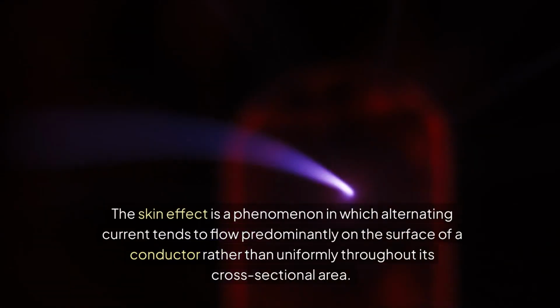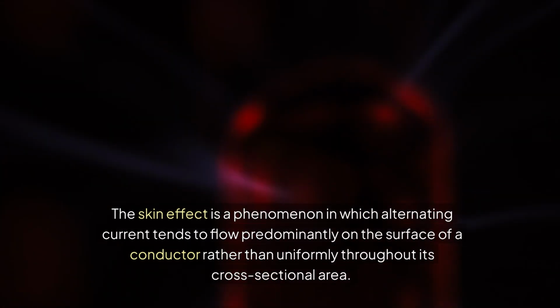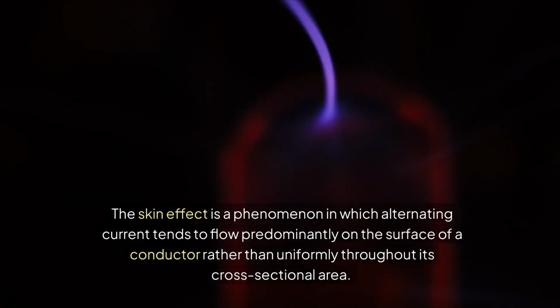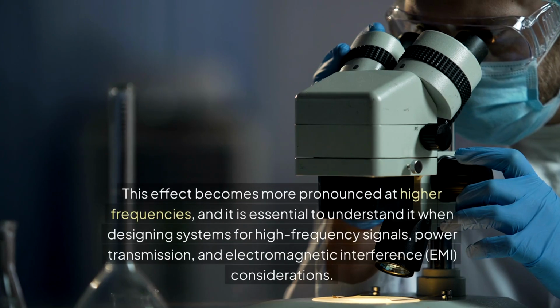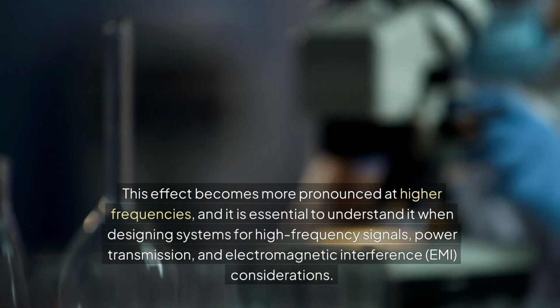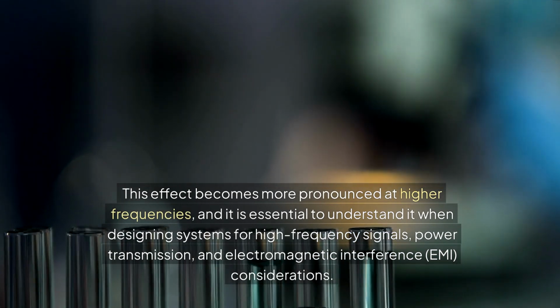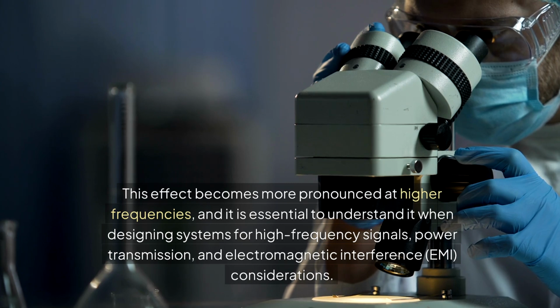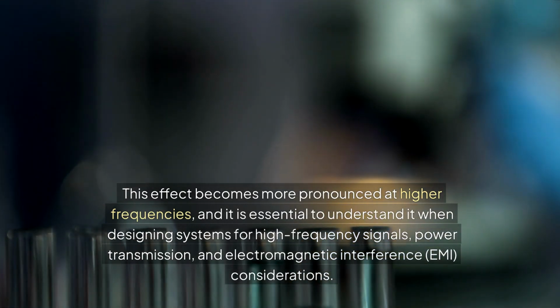The skin effect is a phenomenon in which alternating current tends to flow predominantly on the surface of a conductor rather than uniformly throughout its cross-sectional area. This effect becomes more pronounced at higher frequencies, and it is essential to understand it when designing systems for high-frequency signals, power transmission, and electromagnetic interference (EMI) considerations.